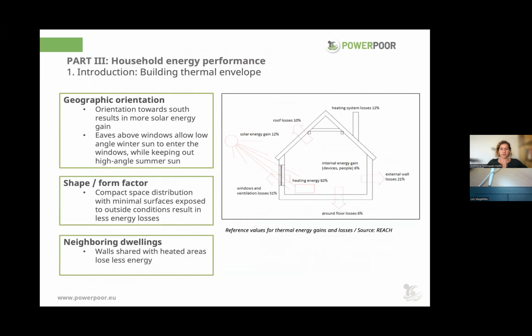Next, it is important to understand if the orientation of the house, of the envelope, is good or not. In Greece, if we have a south orientation, this results in more solar energy gain, which in the winter is something that we want. And if we have eaves above the windows, this can reduce the summer sun from entering the house and creating an overheating situation.